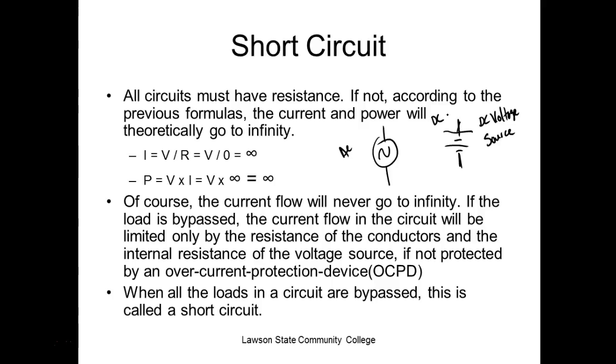But as soon as I hook up a regular battery across a load, right? So go out there on your car, put your battery across there, don't crank your engine, and turn on your headlights. What's going to happen to the output of that battery? It's going to drop. What's dropping that voltage? The internal resistance of the battery. That makes sense. Y'all understand that?